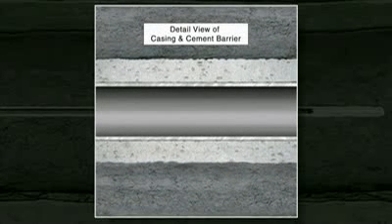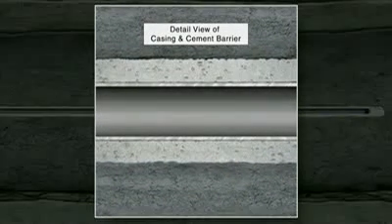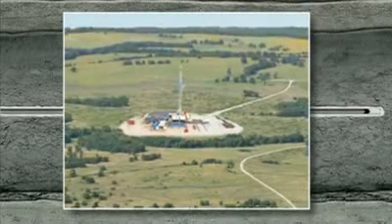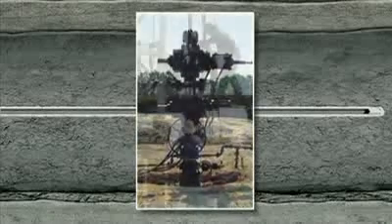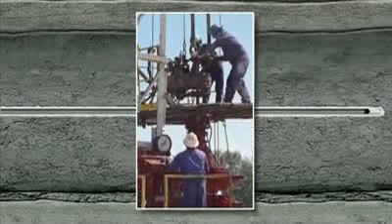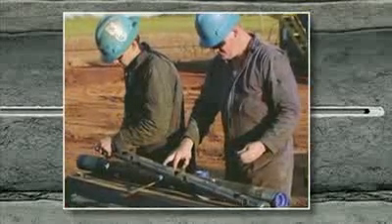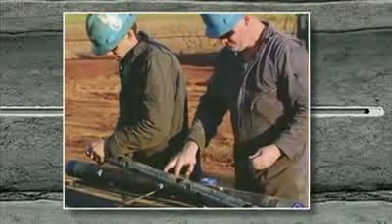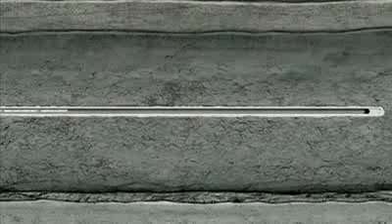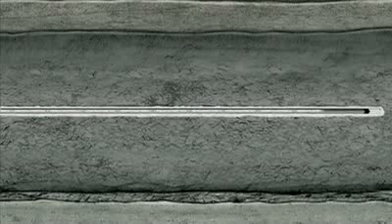What happens next very much depends upon analysis by technical experts who look at the rock cuttings, samples, and other tests carried out during the drilling of the hole. If gas is present deep underground, it is expected to be trapped and must be made to flow using a technique called hydraulic fracturing. First, deep underground holes must be made in the casing.